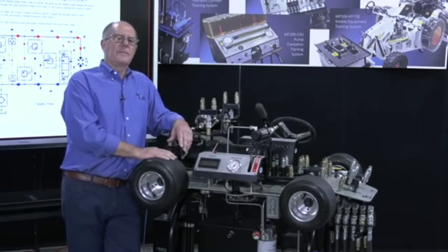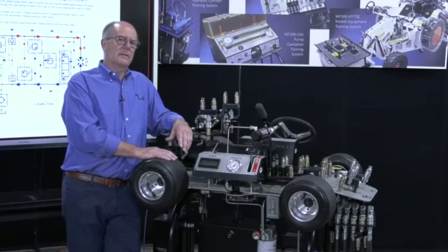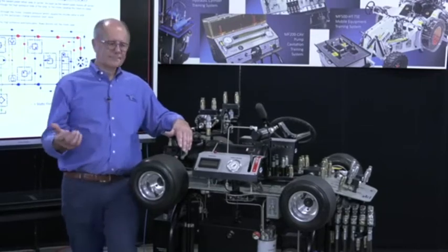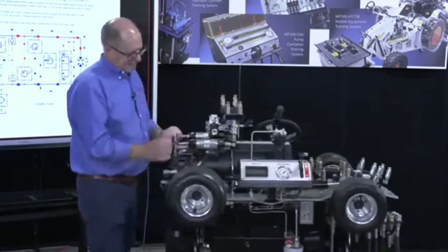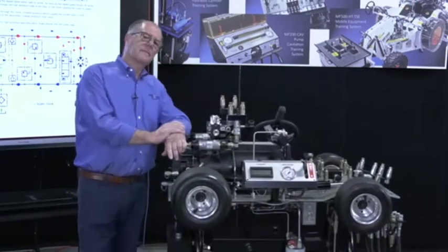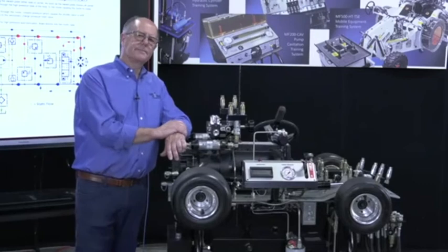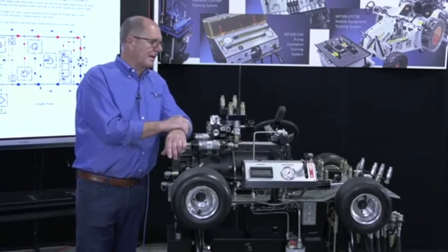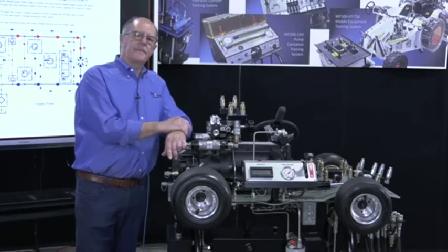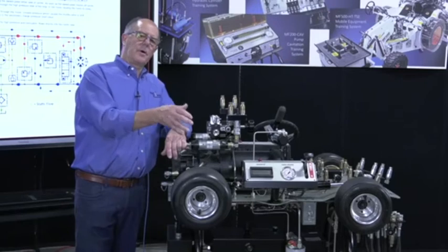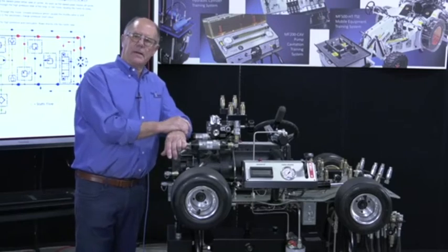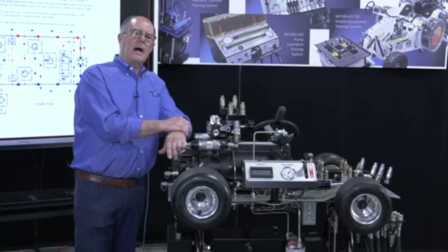Then we talk about using thermal imaging. Sorry, I'm just not a believer in any kind of thermal imaging for troubleshooting. And here's why. I've got a check valve and a relief valve in the same body, and it's hot. Which is leaking? I don't know. If you take a directional control valve, for example, on a front-end loader that's got an anti-cavitation valve and it's hot, is it the spool and the bore that's leaking, or is it the cartridge valve? And if it's a 10-section valve on a crane, why would you take the whole thing out? It's pointless.